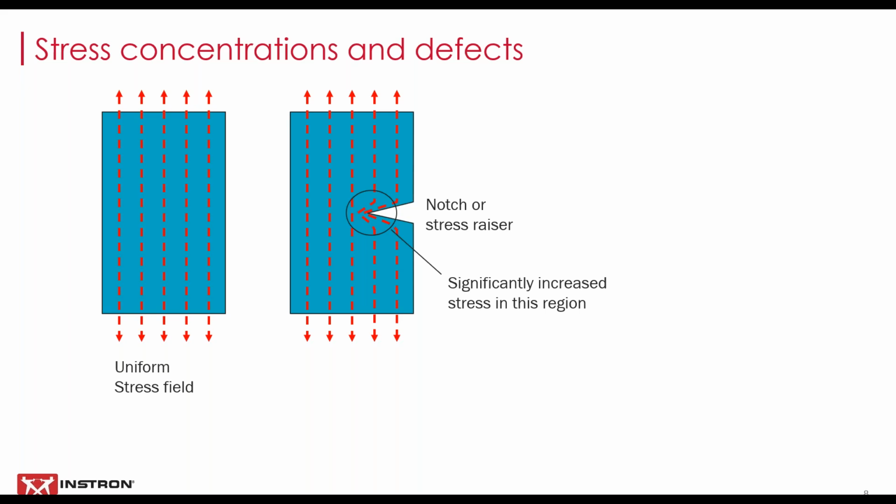Now, if I cut into it, I've got the same amount of force, and it's nicely spread at each end, but we've got to force it through this tighter section where there's a notch, and hence it gets termed a stress raiser, because the bit near the pointy end of that notch is carrying a much higher stress than the rest of the width. And so hence we start describing this as a stress concentration.